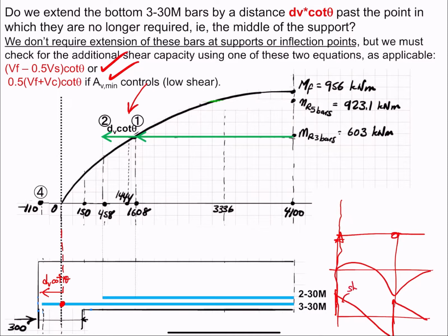So it's reasonable to think that we are in the first case, in which we have to quantify or use that anchorage force, because we are so near the support, and there is a large shear there.